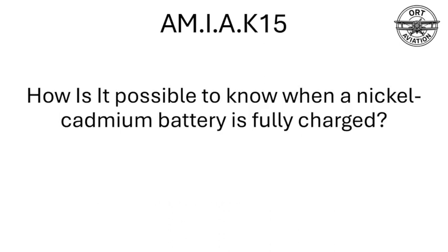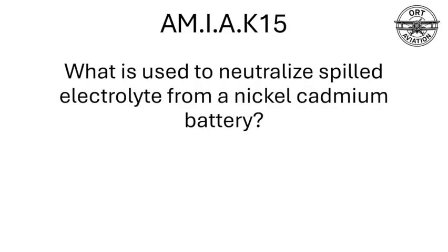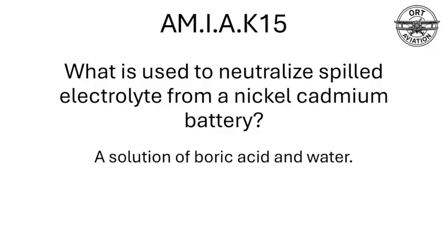How is it possible to know when a nickel-cadmium battery is fully charged? Completely discharge the battery and give it a constant current charge to 140% of its amp-hour capacity. What is used to neutralize spilled electrolyte from a nickel-cadmium battery? A solution of boric acid and water.